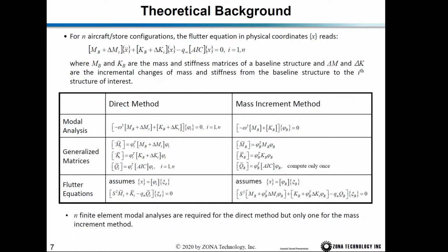That means if you have an aircraft with stores, you do not include those stores in the aerodynamic model, because we assume the underwing store influence on the flutter result is small. However, as we showed before, any aerodynamic component attached to the wing tip may have a large influence on the flutter solution.